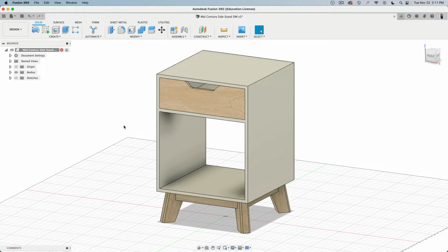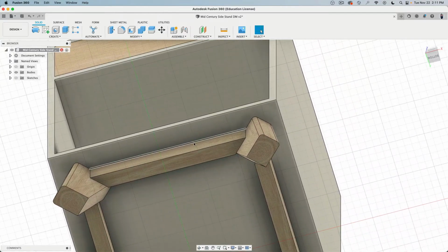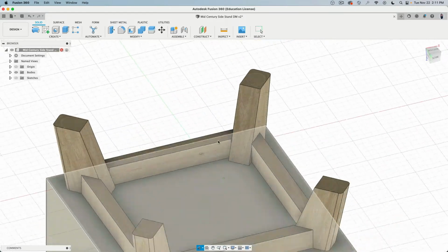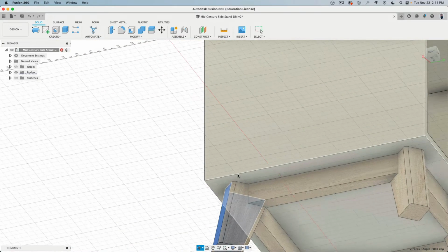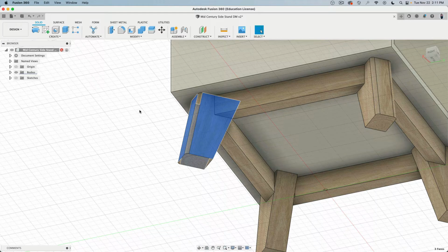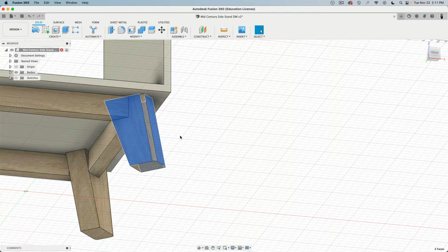Before we export everything to Blender for rendering, we have to adjust our scene here a little bit. The main problem we will encounter is that the wood material that's being used in this design here is a volumetric, a 3D material. You only have access to this inside Fusion and in no other program. So the shortcut is that we will create individual screenshots of the wood material from these views and then glue them back onto that geometry.